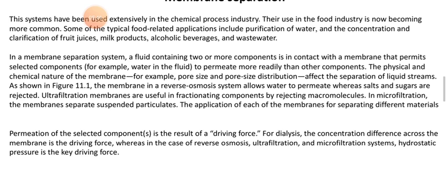Now, permeation of the selected component is a result of the driving force. For dialysis, the concentration difference across the membrane is the driving force, whereas in reverse osmosis, ultrafiltration and microfiltration, hydrostatic pressure is the key driving force. What is the meaning of this driving force? Driving force means a certain force is required in order to pass the liquid through the membrane.